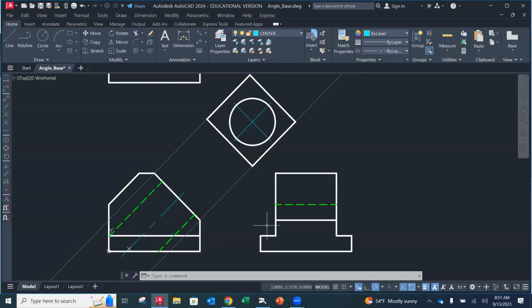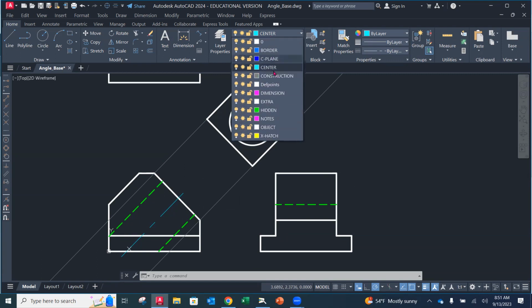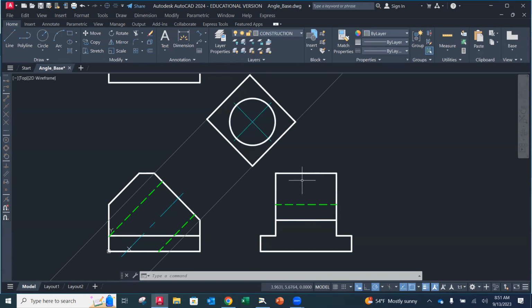Okay. So we are going to project over these two lines. So we're going to use our construction layer. We're going to work on the right side first. So I'm going to go draw X line. And I'm going to put my orthographic projection back on, not the polar. Well, the polar would work because we have it at the 90, either one actually, because it just adds in the 45.